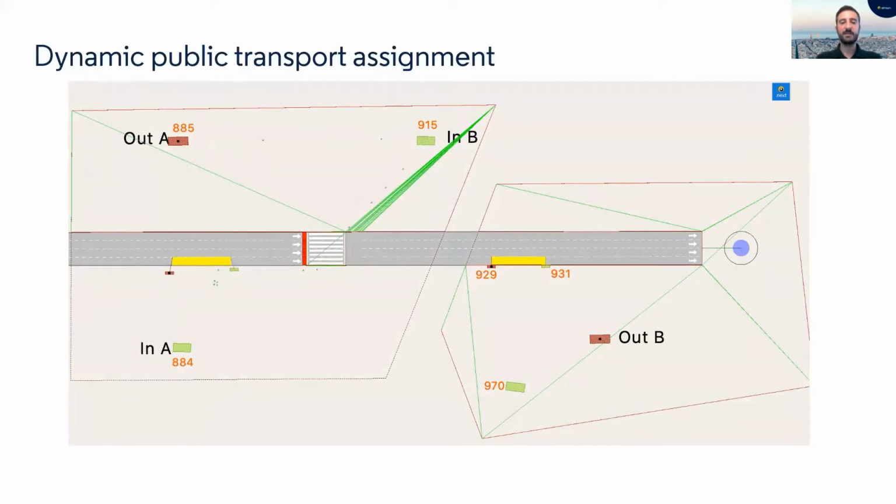Basically, it gives pedestrians the option to take public transport to reach their destination instead of just walking from A to B. With Legion for Aimsun, the choice was offered for pedestrians to reach a bus stop as a destination, and in the OD matrix, the option to define a certain number of pedestrians that alight from that location to a bus and then define a distribution of destinations. We're not talking about this.